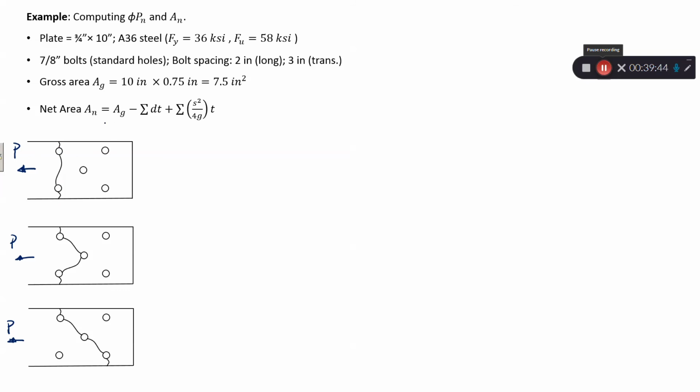It will not fracture over here. It will fracture along the cross-section closest to the load P. Keep that in mind, please. Let's examine the failure pattern. Like I said, it probably will fail along the straight line closest to P, or along the zigzag path like this.